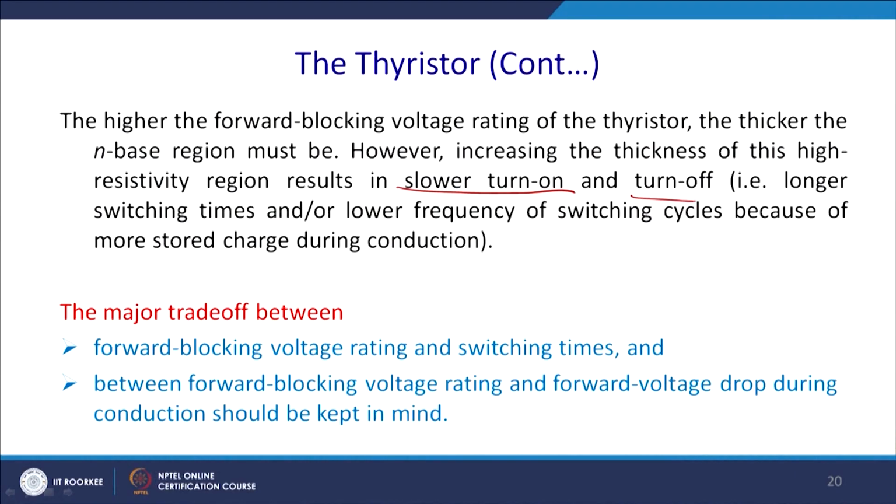when you may have a natural commutation in case of the rectifier operation, when you apply it to the AC source, you get a negative voltage applied cathode to anode. So, thus turn off also will be slower, and it will be suitable for low frequency switching devices, because most of the trapped charge is required to be removed, and that takes a lot more time than in the faster devices. So, there is something we require to trade off, we have to choose according to the applications.